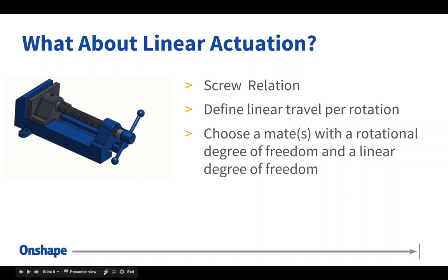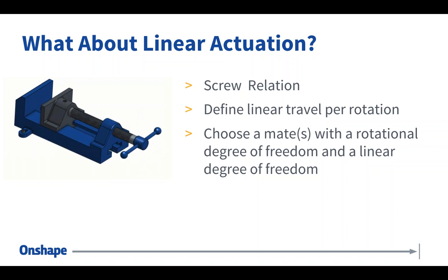Question. So a mate is a collection of parts. Not sure I understand the term. No, the mate is how we put the parts together. The assembly is a collection of parts. So an assembly is a collection of parts. A mate is how we position those parts relative to each other. And the mate also defines how free they are to move.